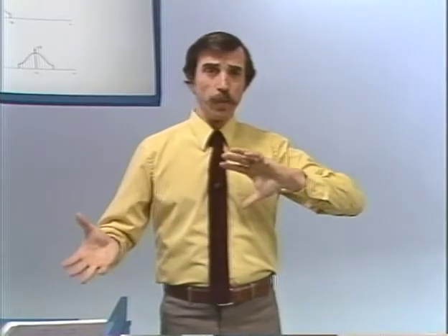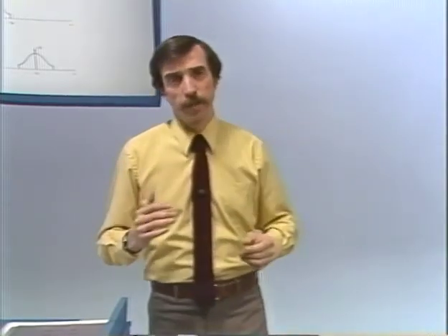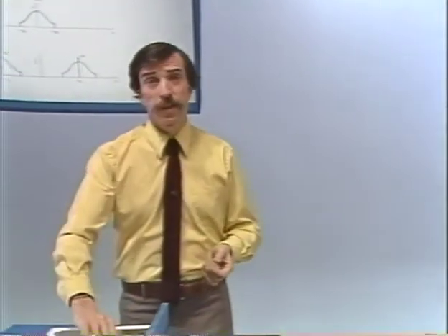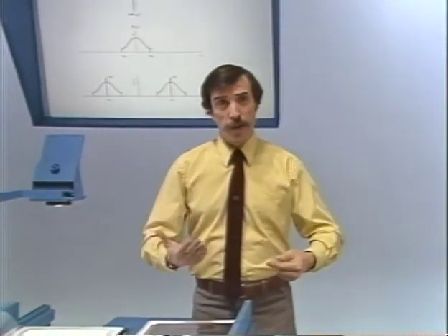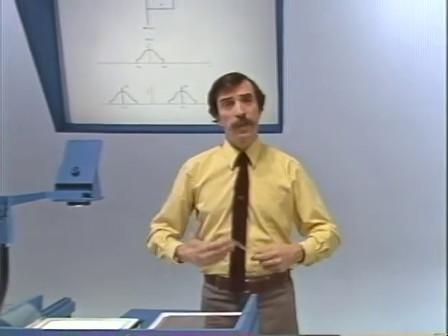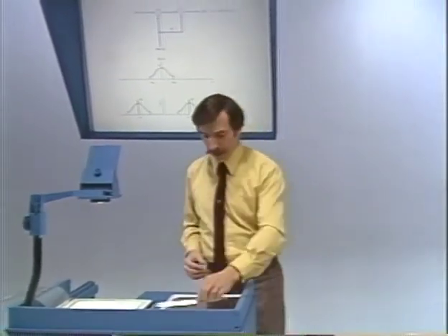And so in satellite communication, you would use synchronous modulation and demodulation, whereas in typical consumer-oriented broadcasting, you would use an asynchronous system and transmit more power even if it's inefficient, so that the demodulator can be simpler.